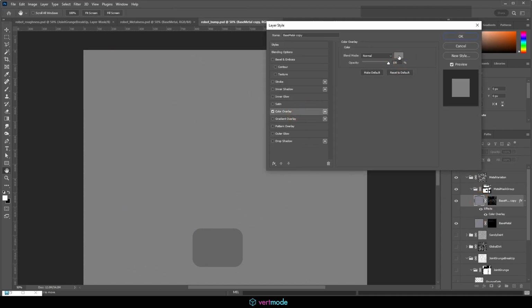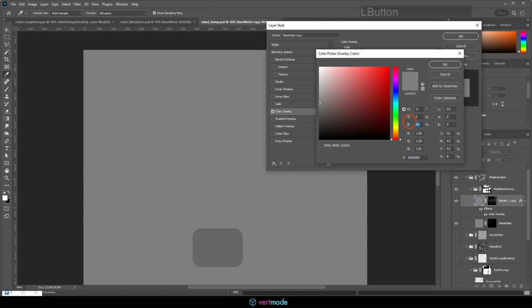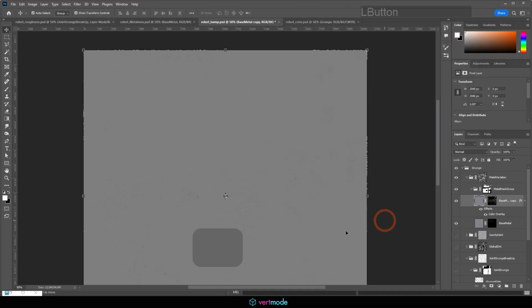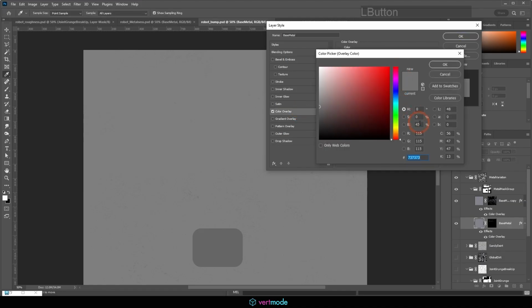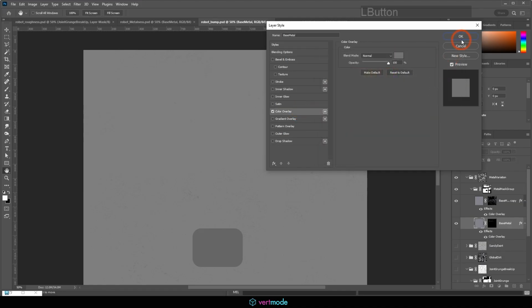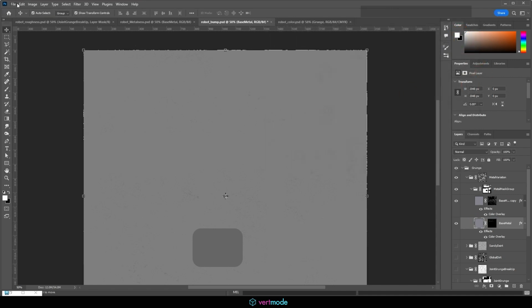For the color overlay here, I might go ahead and set those to be 30. That'd be slightly deeper than the screen. Or I might even set them to be 45, which would just be slightly deeper than the surface. Let's start with that. And the reason why is I have a couple of these around the screen, and you wouldn't necessarily want this to be cut all the way down to the screen. So that, or I can make the screen deeper. Either one would work, but we can see how that looks at 45.